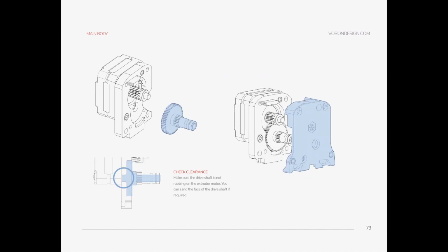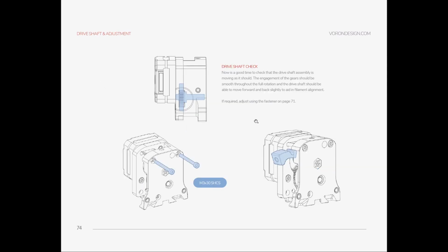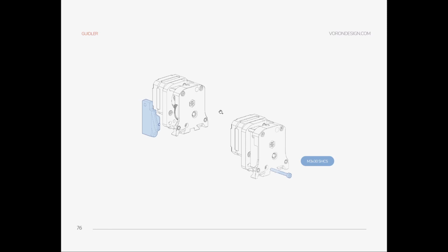So I checked and found that my grub screw was not flush or had gone deeper from the pulley, so the grub screw was powdering my 3D printed part. Be careful about that also. In here especially, the grub screw needs to be at least flush with the gearing or it needs to go deeper. And just follow the manual in here.